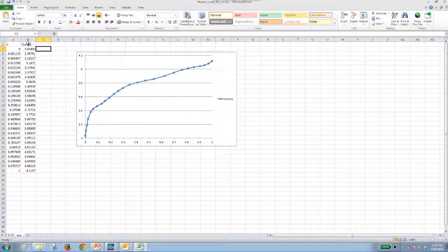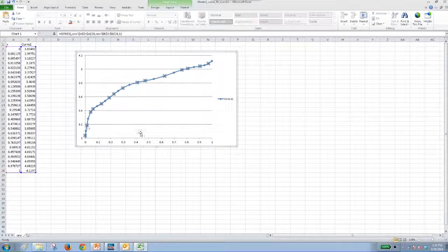So the voltage of the battery is given by the battery state of charge, and it's described by this table. We can either use this table directly in the MapleSim model using the lookup table, or you can use the curve fitting capability in Maple to describe the open circuit voltage of the battery as a function of the state of charge using a smooth function.